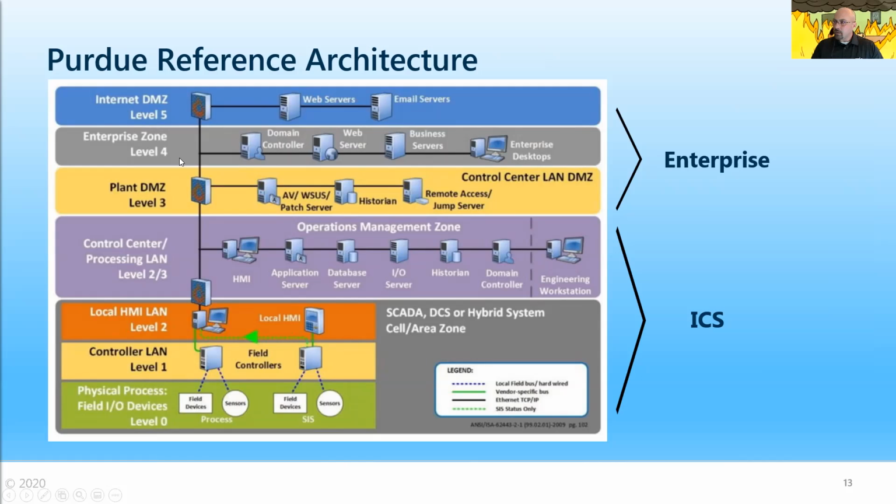It's also important to note that with respect to ICS networks, typically levels 4 and 5 are considered untrusted. These would be untrusted zones with firewalls. A lot of asset owners and plant operators do not allow any connections in from these. They consider those to be as secure as an internet connection. And typically adversaries will have to get down into levels 0 through 2, in the ICS SCADA zone, in order to impact the systems.